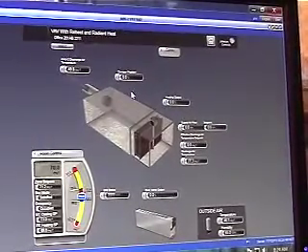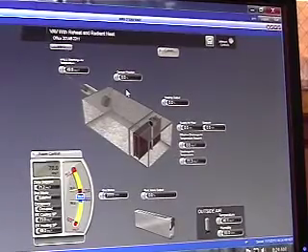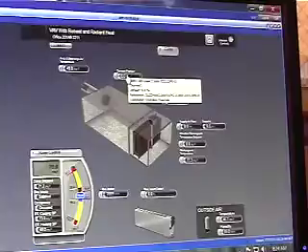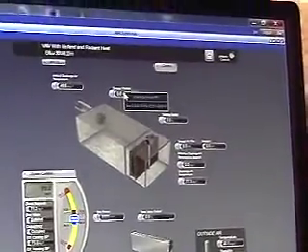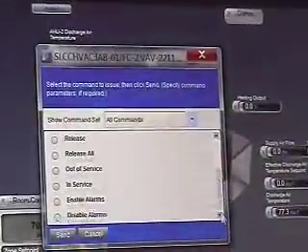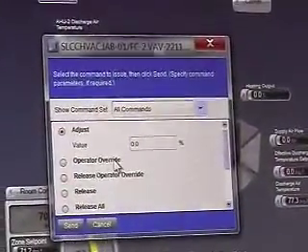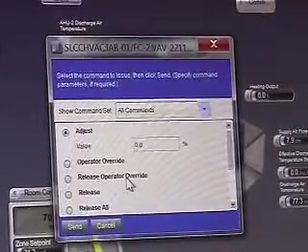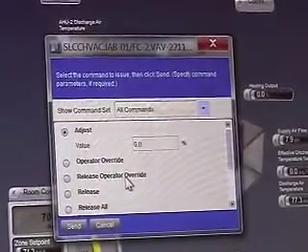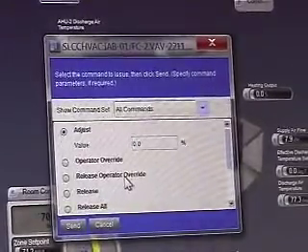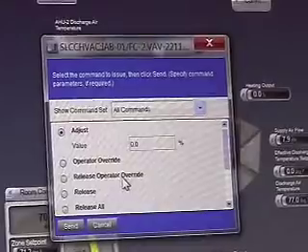From here, as you guys probably already know, there's a couple of cool things you can do. One, you can make a command. So if you click on one of these boxes right here, right click, you can hit more commands, which will give you the ability to make adjustments. One thing I would always recommend doing is whenever you're changing something, always do an operator override if at all possible. That way it gives you a quick ability to run a report and see what was overridden, and just helps keep things simple.